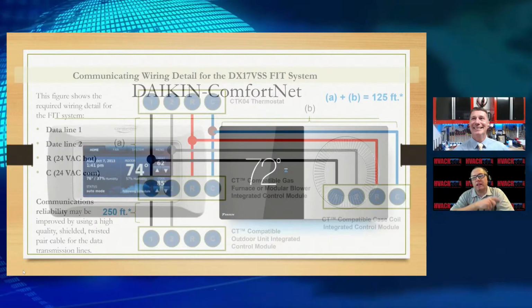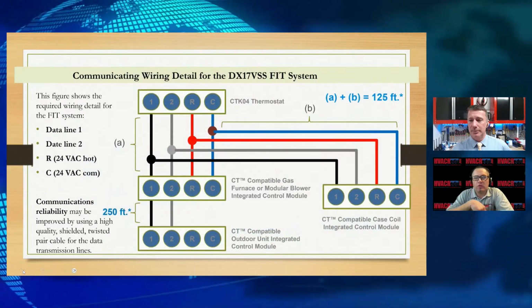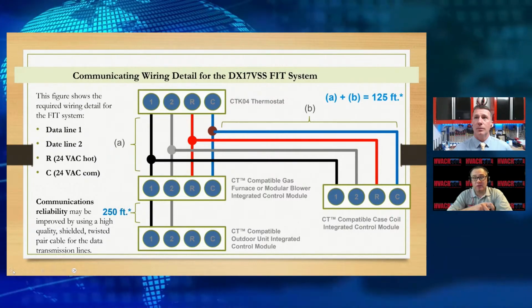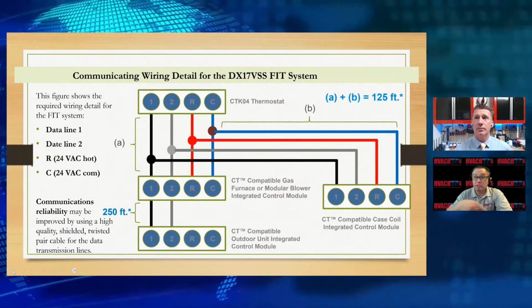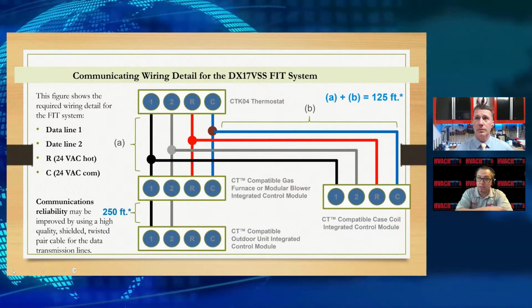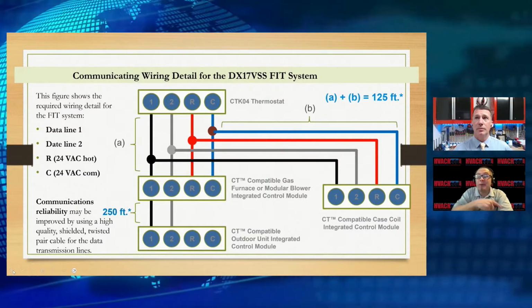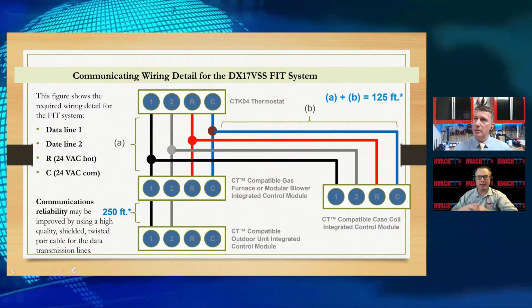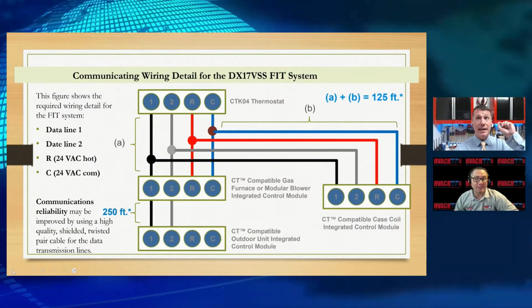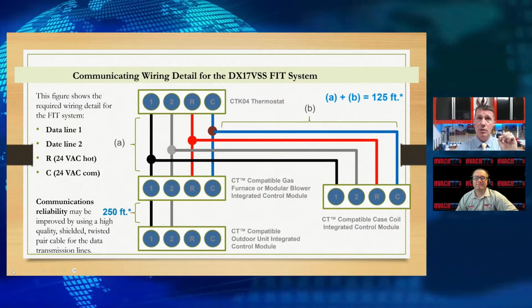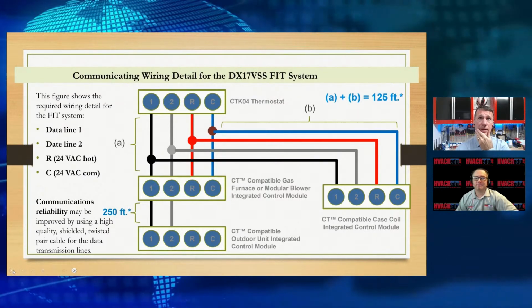Yeah, you made mention that we get that 24-volt transformer from our indoor unit. Do keep in mind this is unitary, usually a split system. Now, when we talk about a ductless split system, it's coming from the outdoor unit. Everyone's going, "Hey, time out, that comes from the outdoor unit." Exactly, in a ductless system, our inverters that have a power supply at the outdoor unit will typically have their own as well. And we'll show you a little bit on that.